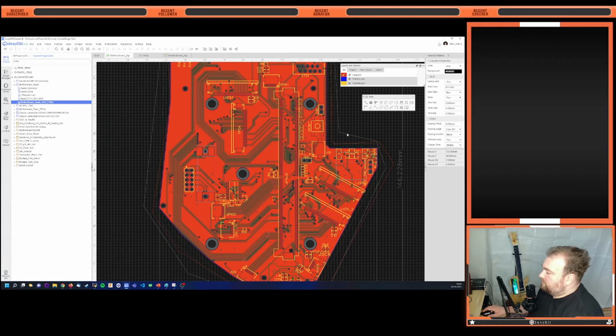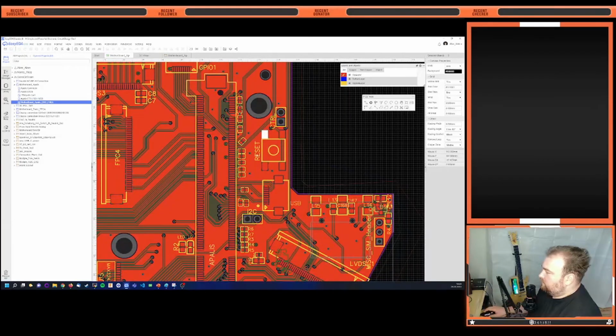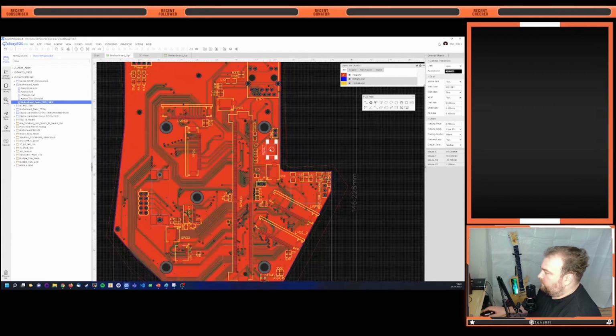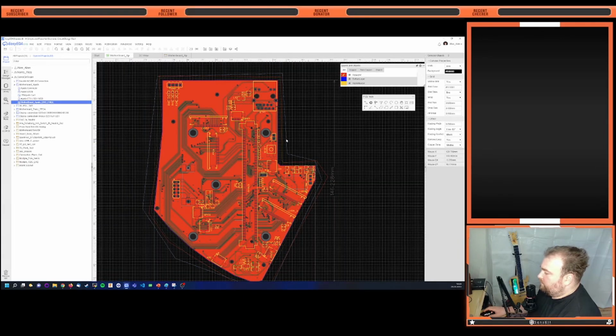If you ever design such a board, I give you one little piece of advice. Every time you design a little bit complicated board and you have the opportunity to add a little tactile switch for the reset, do it. In the long term, it will be great for you to have this, because to have a physical button to reset the whole system is really a great thing.